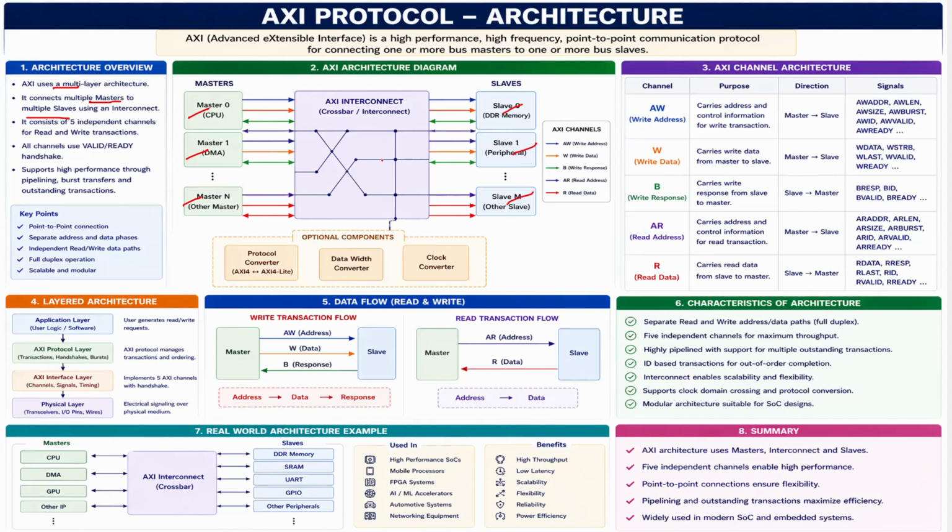So point to point communication is possible, and cross connection is also possible. Master 0 can connect with slave n, and master 1 can also connect with slave 1, and connecting to slave 0 is also possible. That cross connection is also taken care of by this AXI interconnect.